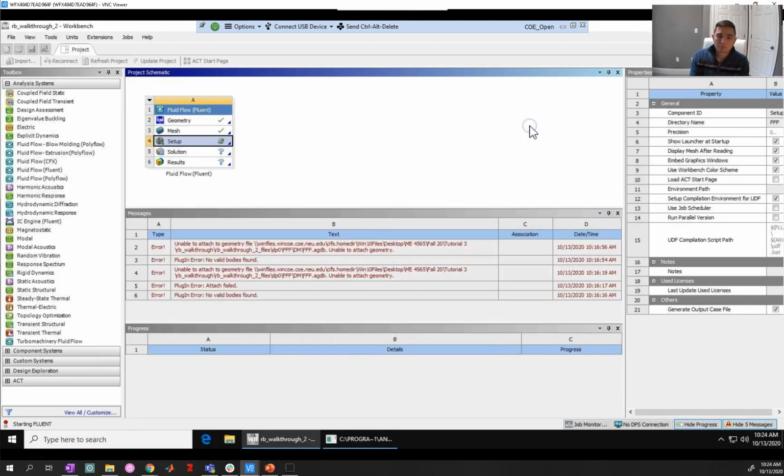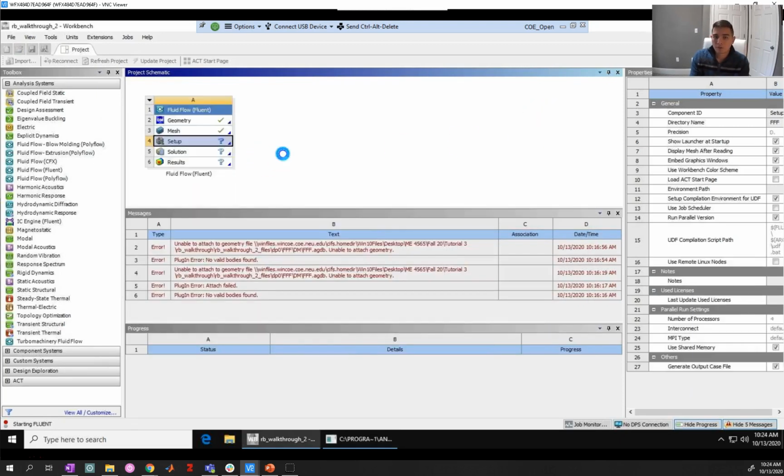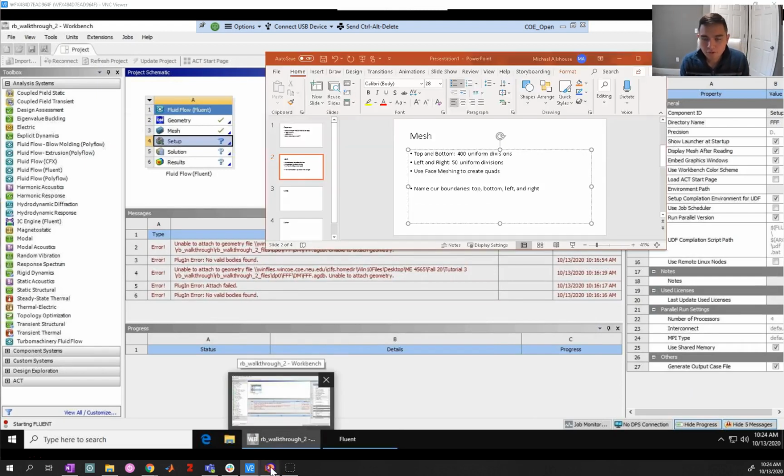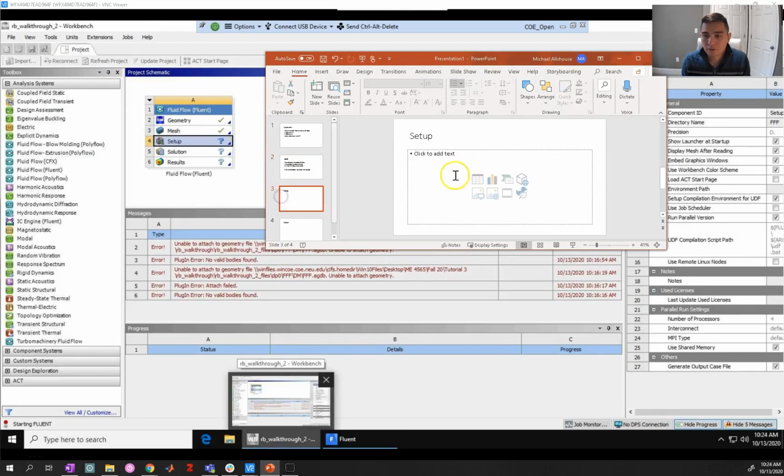Okay. So Fluent will be starting up. So we'll just add those things to our setup. So you can use double precision, and on VMware machines, you can use 4 processors. Okay.